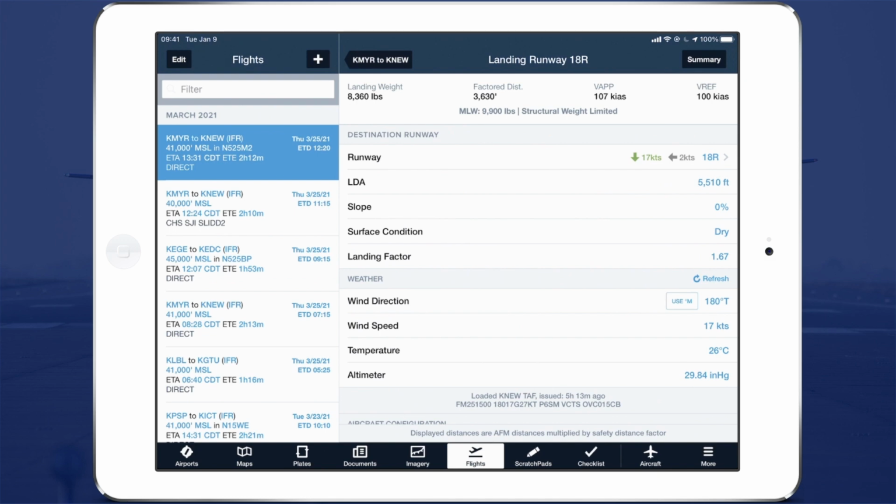So from an operational standpoint, landing factors are a great thing. If you see that you cannot land with that 1.67 factor, for example, pretty good idea that you might need to either consider a different runway or really make sure you're flying exactly by the numbers. But as Michael said, it's essentially based on no flare. So, most aircraft, 50 feet, you're going to idle, you're at VREF, and you're doing a slight arrest of the descent, but that's all you're doing.